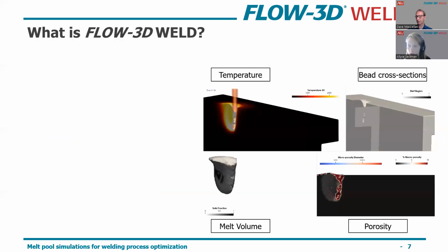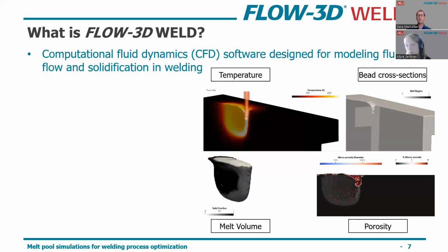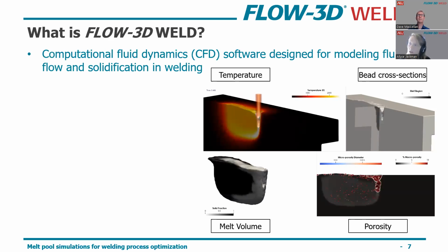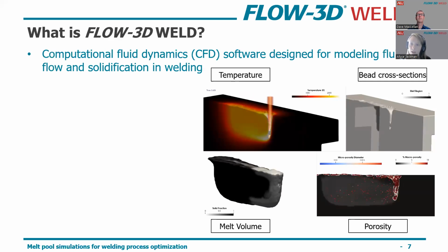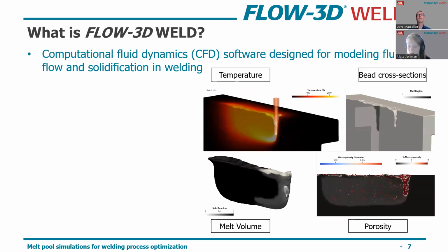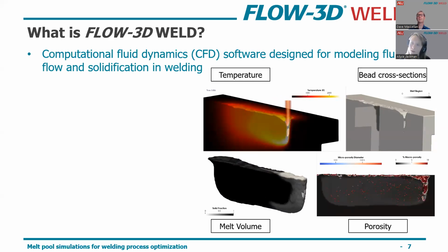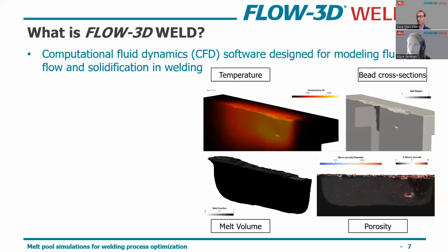So Flow3D Weld is the software that we develop. It is a computational fluid dynamics software at its core, but it is designed specifically to model fluid flow and solidification in welding processes. So we can look at things like temperature evolution, predict bead cross sections, predict the melted volume, the surface roughness, the relative porosity, both micro and macro porosity.